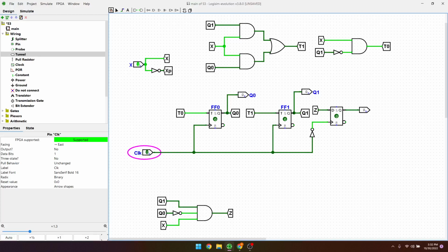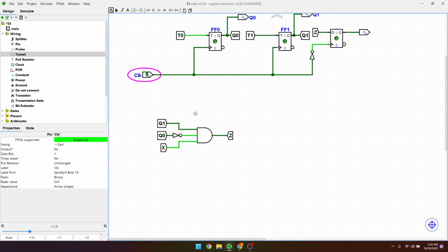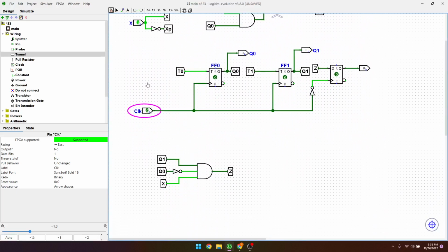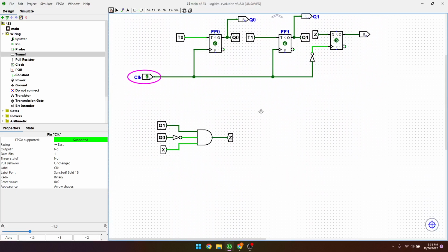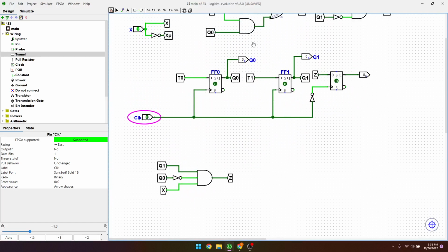And lastly, just explaining why this is a Mealy machine and not a Moore machine, and it's because X is part of Z here. So X is our current input, like whether or not we're putting in a nickel. And if this was a Moore machine, X wouldn't be part of Z, and Z is ultimately what our output is.